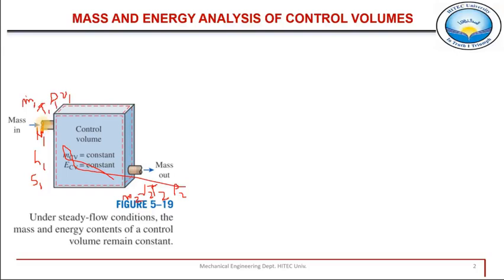For example, at this point the mass flow rate has a certain value, 1 kilogram per second. Temperature has one single value. We can assign one single or averaged value at the inlet. For example, it is 20 degrees Celsius, pressure is 1 bar, specific volume is 0.1 meter cubed per kilogram. So we can assign a single value to this whole mass of the fluid which is entering, and when it is leaving, the same whole mass has now some new value of specific volume, temperature, pressure.